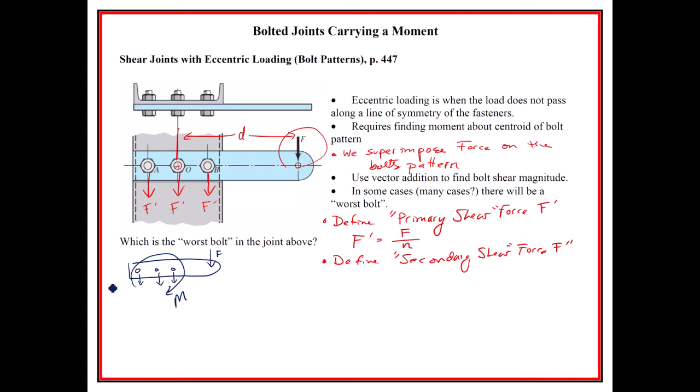So we can take a look and see what kind of equivalent forces are required to generate this same moment that are placed onto the bolts. And those equivalent forces, F n double prime, are going to be equal to that moment times a parameter R, I'll explain what that is. I said A, but I meant Rn. And that's divided by RA squared plus RB squared plus RC squared, up to Rn squared. So however many bolts there are, there's going to be this R. And that R is defined by the bolt pattern.